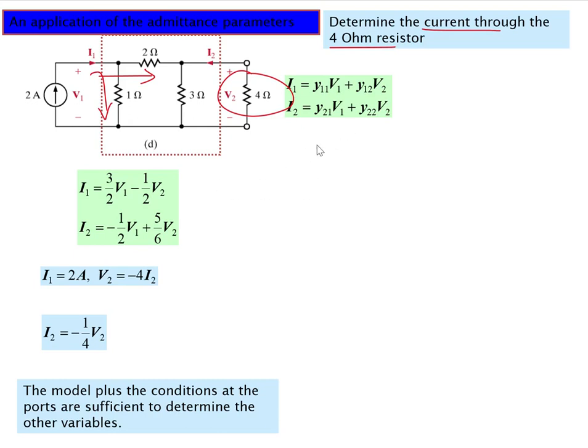First we are using these two equations for calculating our y11, y12, y21 and y22. For that we are using the same method: first we remove the resistance of the output side by making it short circuit.